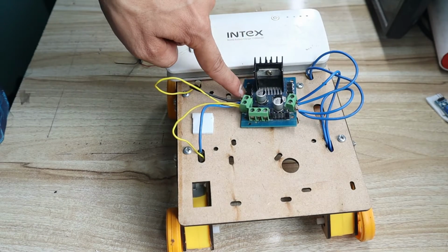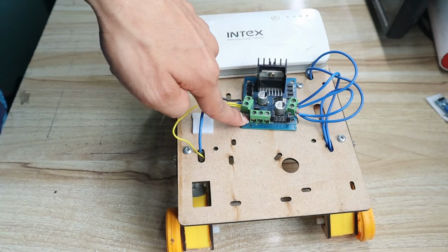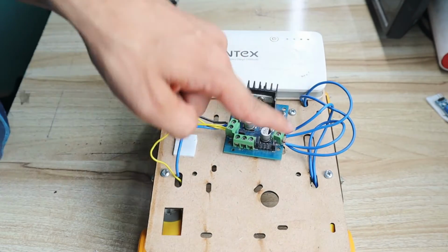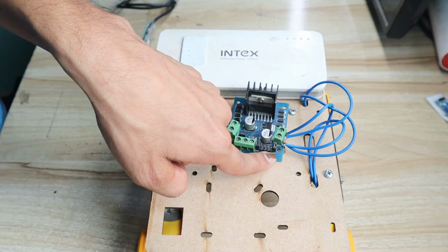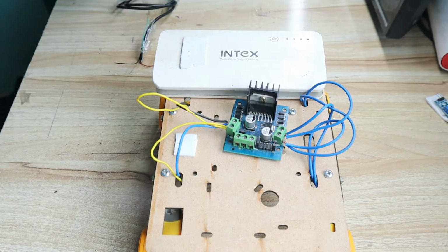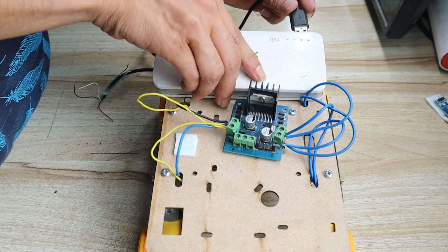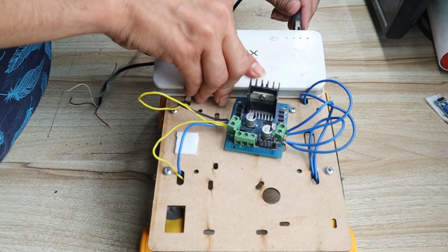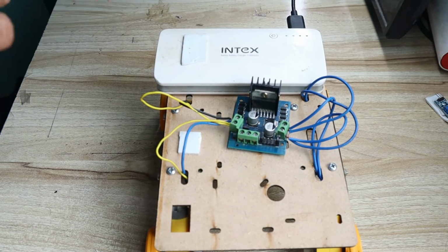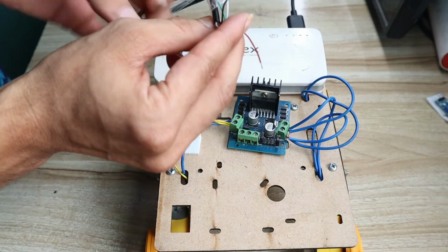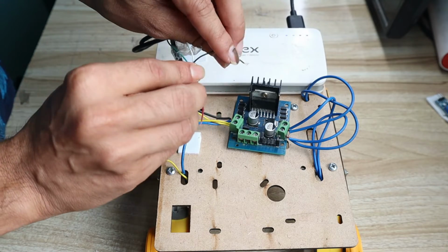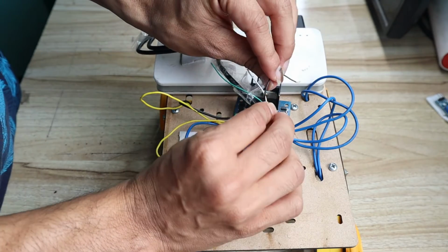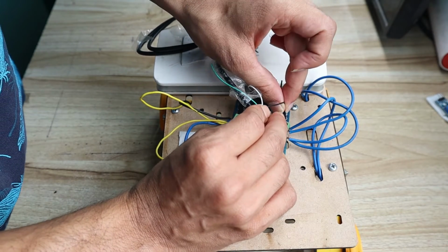Motor output 1 we give positive supply, 2 we have given the negative supply. Same for motor output 3 we will give the positive, motor output 4 we will give the negative. 3 we will give the positive because 1 we gave the positive, so the lesser number we give the positive again. So the motor should be rotating clockwise again,